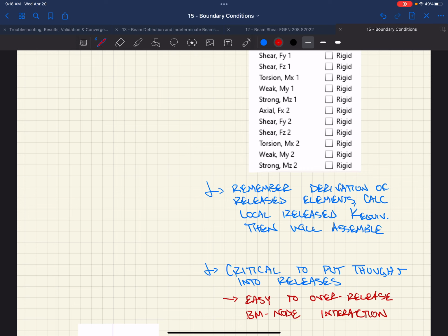Where do you release the beam then? If it's a moment frame, you wouldn't release it, right, because it's completely fixed. Not even outside that cheek plate. It acts as though it's continuous, right? There is no hinge here. This isn't going to be able to rotate freely. It's connected rigidly because this beam in real life extends all the way to the column. But then we add all these cheek plates to it that allow us to transfer shear and moment across this intersection, the connection here.